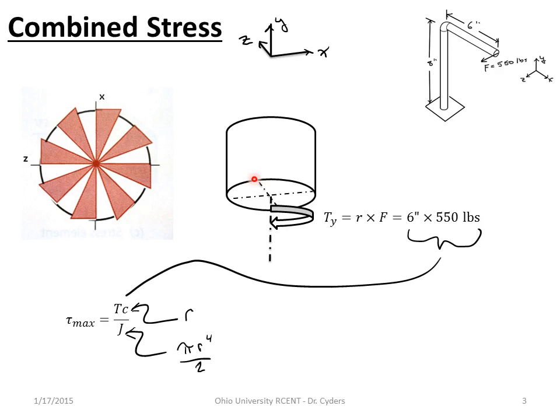So where we're crossing the z-axis, where the z-axis is radial from the center of the circle, we're going to have tau xy. So at point A, I'll have a tau xy, but at point B, on the x-axis, I will have a tau yz. And this is significant if we're trying to remember where to combine our stresses.